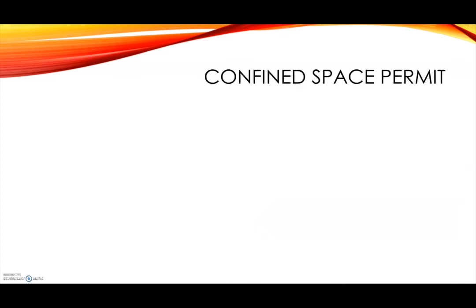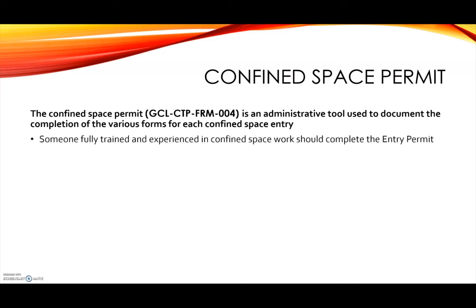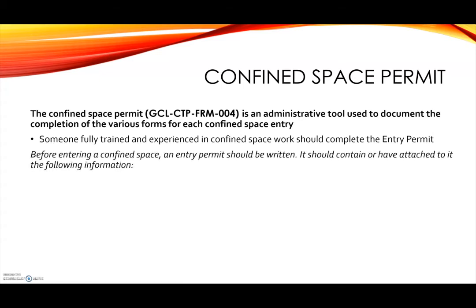Confined space permit. The confined space permit form is an administrative tool used to document the completion of the various forms for each confined space entry. Someone fully trained and experienced in confined space work should complete the entry permit. Before entering a confined space, an entry permit should be written. It should contain or have attached to it the following information: